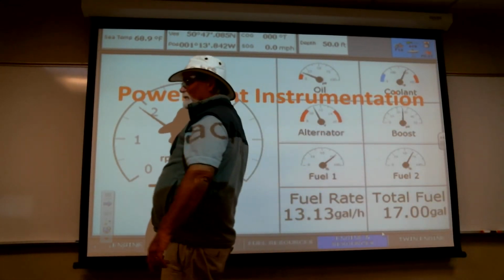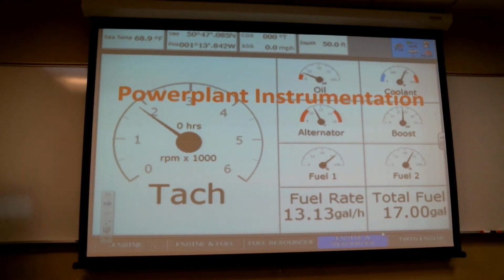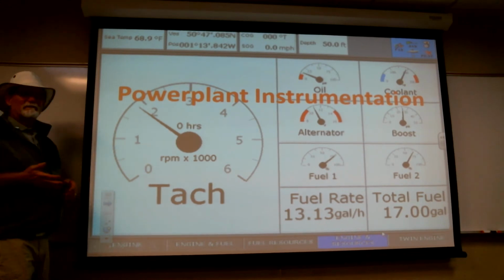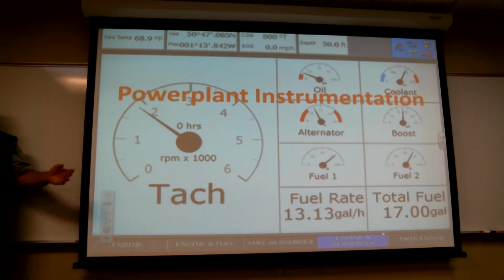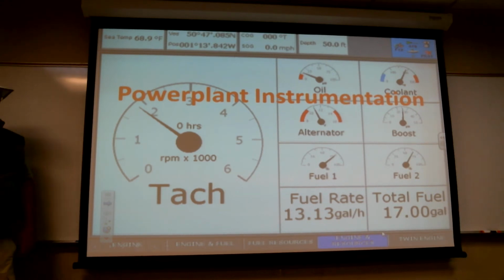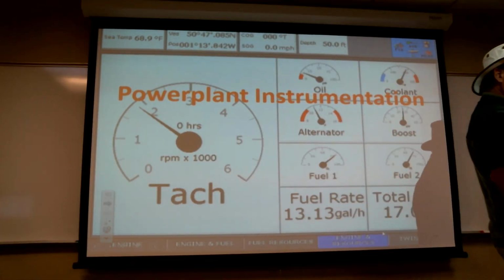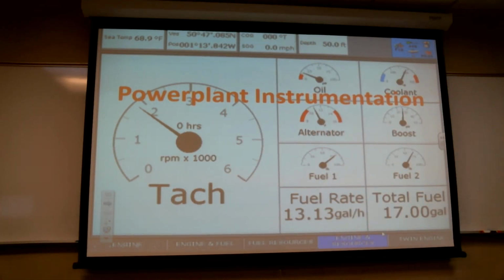The problem is, an engine system that's monitoring engine data, is it really an airframe component or a power plant component? I don't know. It's kind of gray. The FAA pretty much says it's an airframe component. They expect the airframe installer to be installing it all.